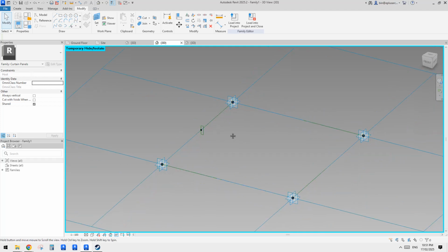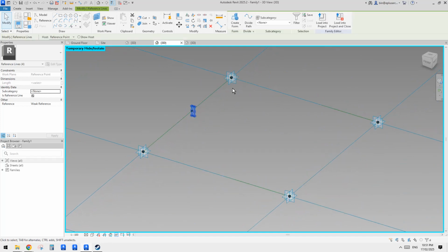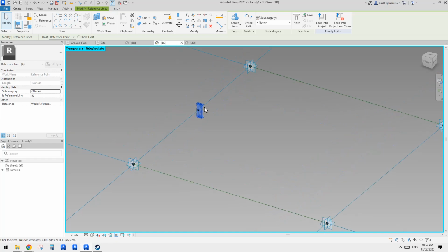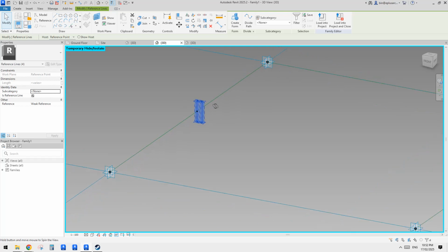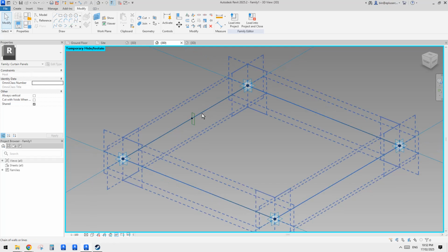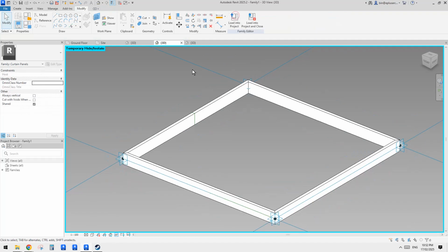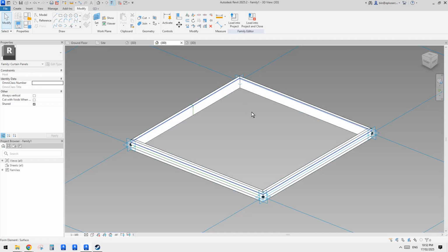Because when we place this profile in a pattern-based family, there will be another one sitting side by side. So we'll just make it 50, so the overall will be roughly 100. So now select all these shapes, select this profile, create a form, and type HR to bring back the glass.